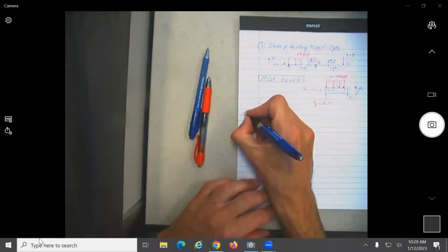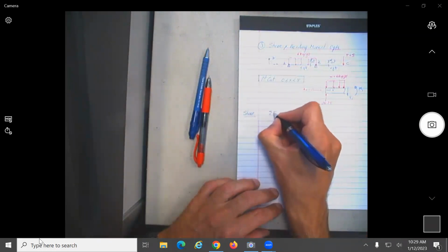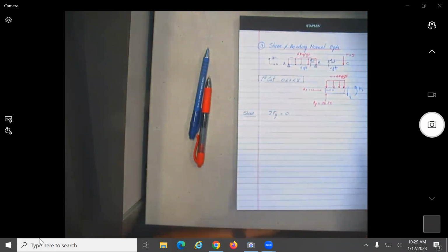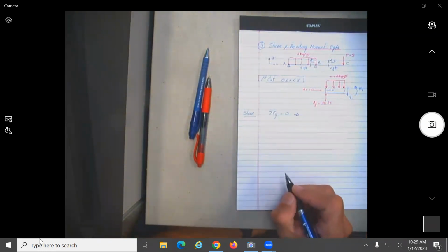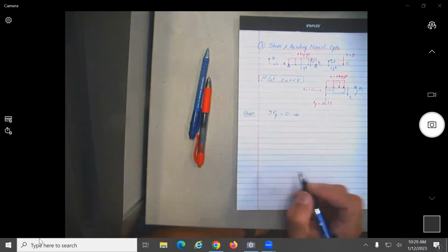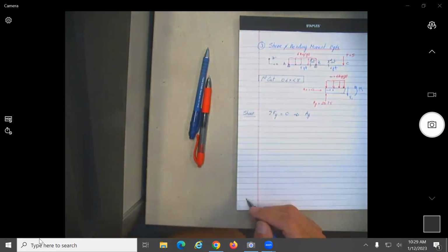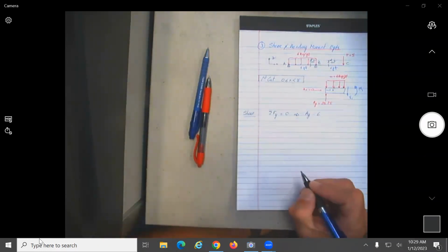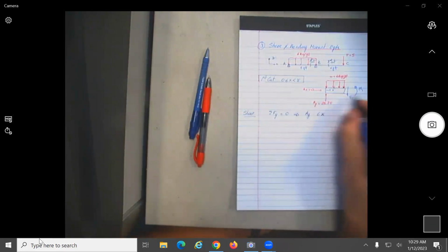Well, in order to find shear, we're going to apply which equation? Summation of forces in which direction? I mean, you can do on the X, but the X is nothing in this one, no? So we do on the Y. And now, what do you have on the Y? I will change the values. I just do it symbolic now, but it will be AY minus 6 what? 6x, perfect. This is the distributed load.